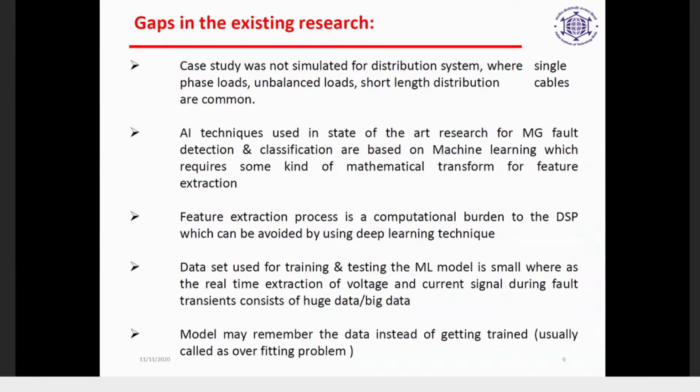What you may have to do is find out a positive sequence component, a negative sequence component, or a zero sequence component in case of a grounded fault, or you may have to find out the harmonics, or a particular total harmonic distortion, and also different features to pinpoint what kind of fault it is. So basically your data comes to you, and then feature extraction is another thing which has to be done. For example, there could be this DFT process which you may have to do on the collected signal for a certain window, and then that feature extraction can be used for the fault identification process.